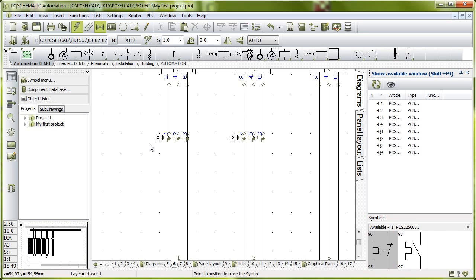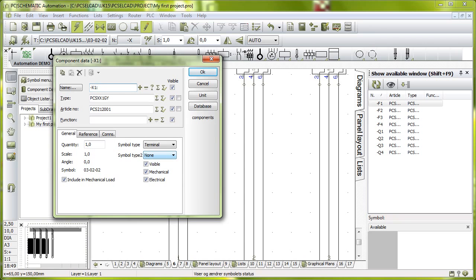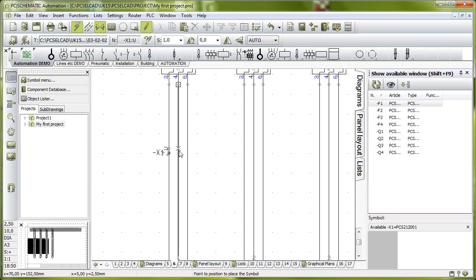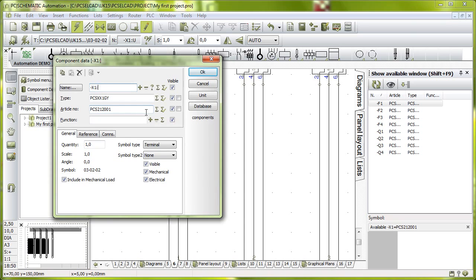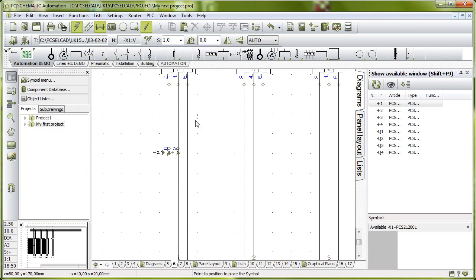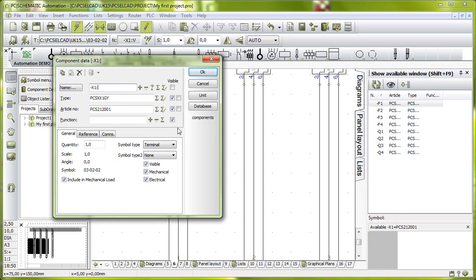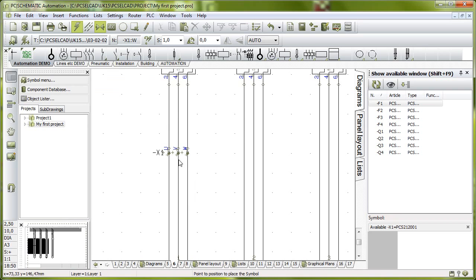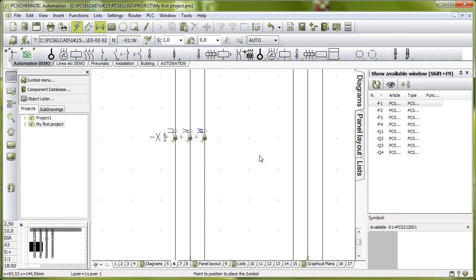And the multi-placement function is simply one that does this, aligns them and counts them and sets one invisible at the other end. However, if this is motors, I cannot count this function, unfortunately. So if I want it to be motor terminals, I'll go in and call it x1:, and I can call it U. And I'll go to this one and call it V and make it invisible, and that's all what the multi-placement function does for me normally. And in this way it'll be called U, V and W.